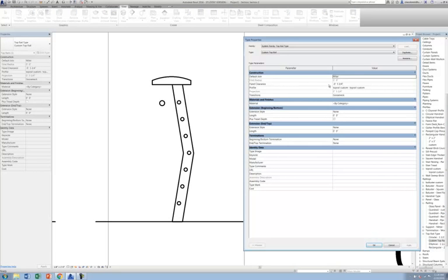this, there's a hand clearance that's actually defined in the second level. So at the railing's top rail type setting, here is where we can define the hand clearance, and it looks like this maybe wants to be closer to like 4.5 inches. We can say apply. Nope, wrong way. So it goes 6 inches. Whoa, minus 6 inches. Closer, minus 8 inches. Too far. Looks like 7 will be just right.